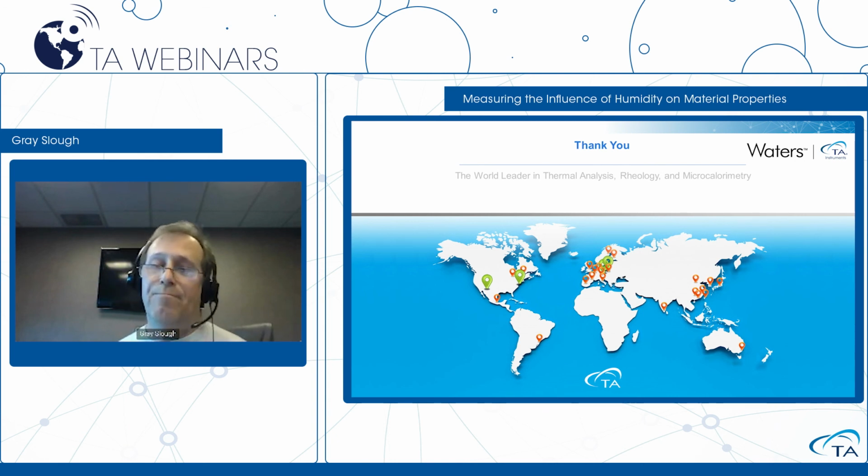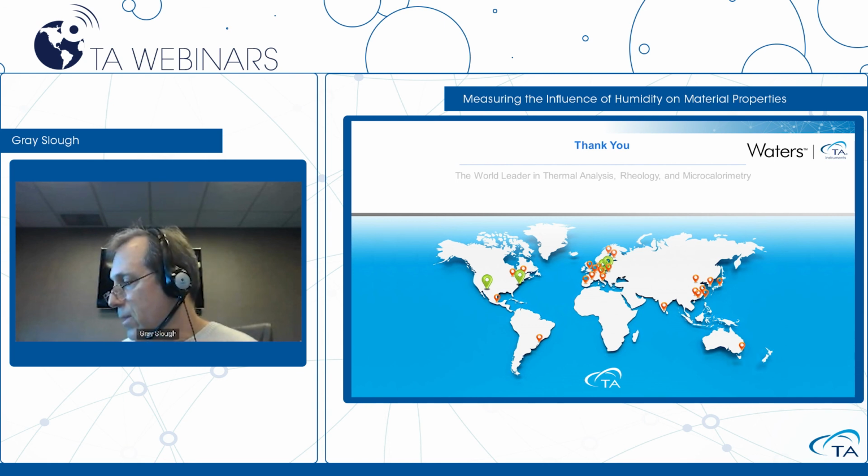There is the knife edge probe, which can be used. Sorry, it's a 3-point bend probe. So you have a sample which maybe looks like a cylinder or a plane surface, rectangular type of sample that's supported on two ends, and then a knife edge probe is brought and rests in the middle of that. So there's 3 points, 2 points of support, 1 point of contact.